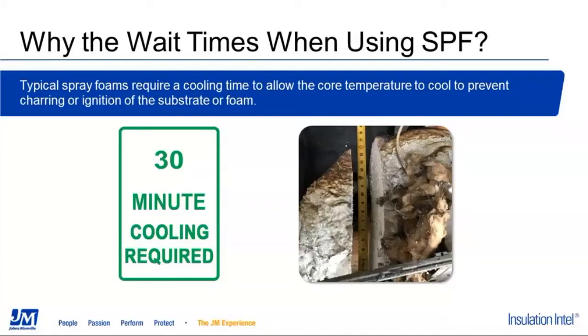In the photo on the right, closed cell spray foam was mistakenly sprayed in a single 16-inch pass, leading to charring. Though you won't see any manufacturers recommending 16-inch lifts anytime soon, it's a good reminder of the importance of keeping heat buildup in check.